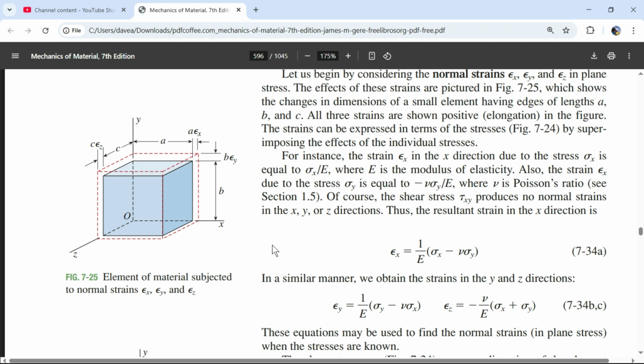And cool. So we have that 29 million to relate a small number to a fairly substantial number. So if stress is equal to 29 million times strain, or if stress is equal to E times strain, then E is stress divided by strain. So here's where we got that stress divided by strain, and right now, I don't know why it's this minus that. But what we did say is we have Poisson's ratio, so we are going to take that into consideration. Oh, and we're in plane stress, so there's only two terms here, so I guess I kind of figured out that we don't have any tension or compression in this y direction. So we're not going to get a Poisson's effect.